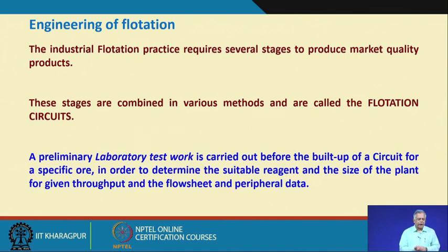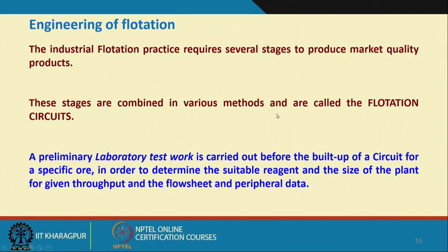I can have a closed circuit crushing circuit, I can have an open circuit crushing circuit, I can have a closed circuit grinding circuit, I can have an open circuit grinding circuit, and I can even have primary grinding and secondary grinding circuits, like crushing, where I can have primary, secondary, tertiary crushing. In flotation also we try to do that. So, these stages are combined in various methods and are called the flotation circuits.